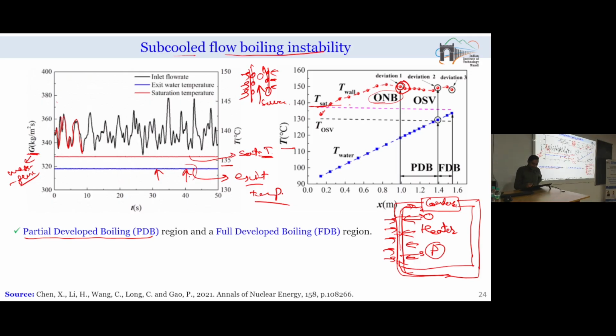However, this bubble will not be able to sustain, but after this decrease we again find that the wall temperature has started increasing. What does it mean? That bubbles are forming, and they are not just collapsing at the moment, but are growing. Once they start growing, we can say that saturated boiling has started. This is how we can distinguish the regimes between nucleate boiling and saturated boiling.